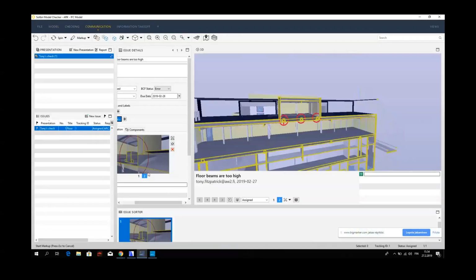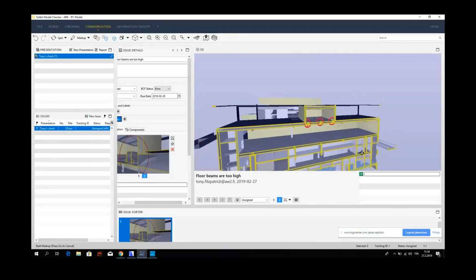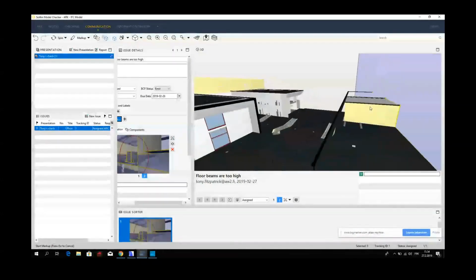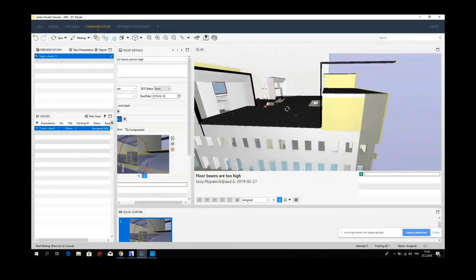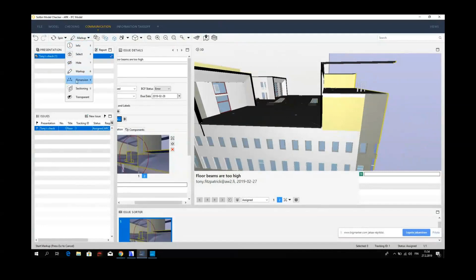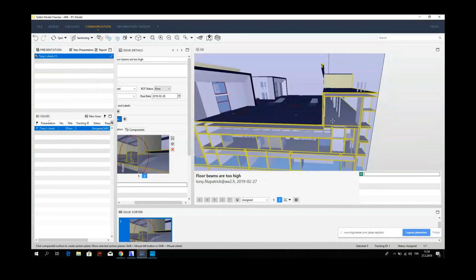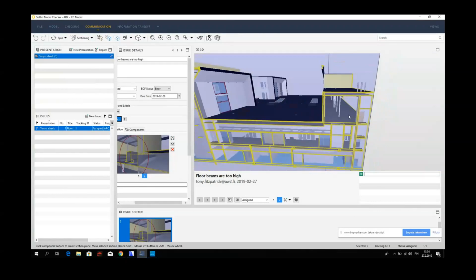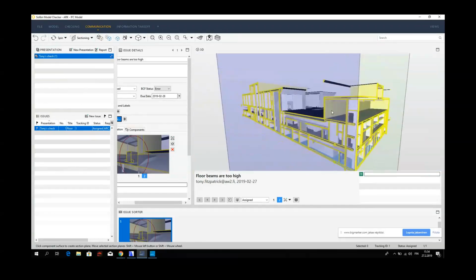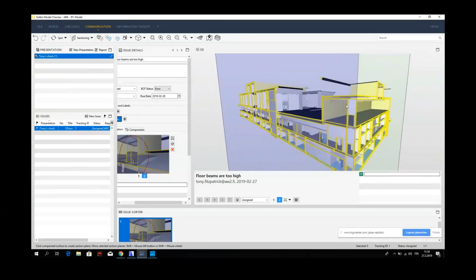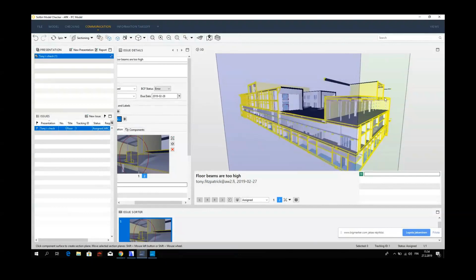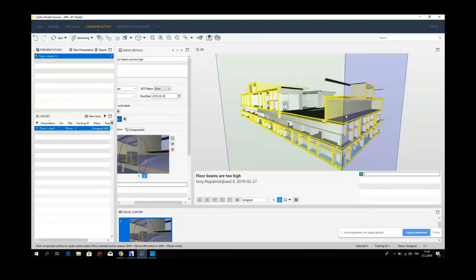And we can also create multiple cut planes. So we section. And it seems that if you wheel mouse with multiple cut planes, it brings them both. If you click and mouse, it just moves the one that you selected. So if you're wanting to hone in on an area, create a box around it, well, you could do that.